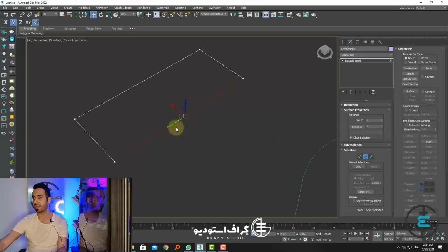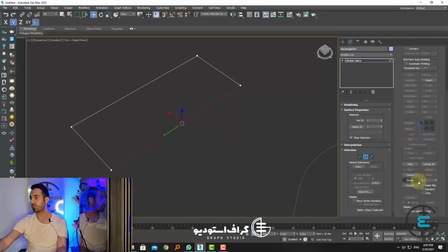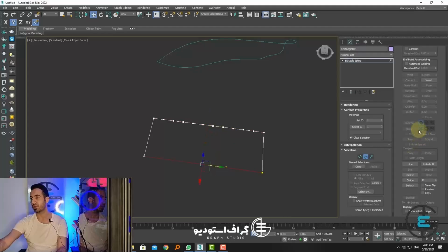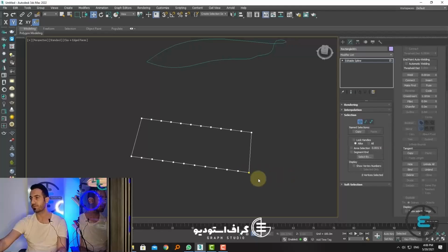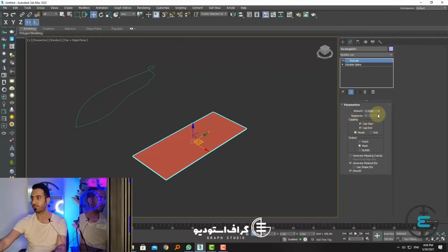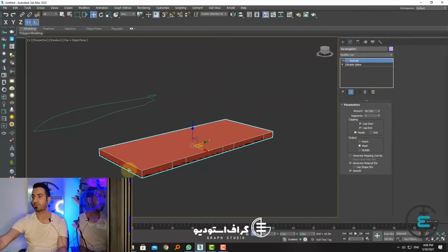I go to the top view as usual, activate Line, activate the architectural plan, and I draw it, guys. When we select this in the Spline section, it has a very practical section. Did you see that I checked this part? After your work is finished, be sure to check that your spline is closed, or that Closed is written here, because we said we have more work with closed splines than open ones. Now, if you want a special project, I'll tell you, for example, what can be done in Spline and Open?